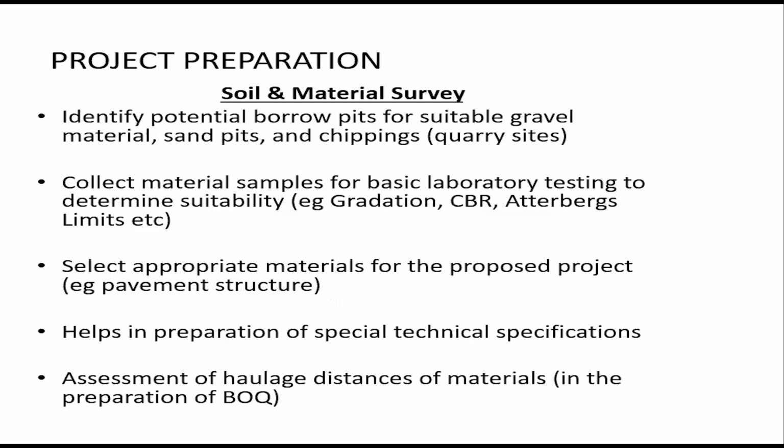Now, for the soil and material survey, you need to identify potential borrow pits for suitable gravel materials, sand pits, and chippings, that's quarries, for the project. You also need to collect material samples for basic laboratory testing to determine their suitability. That's gradation, CBR, Atterberg limits, among so many others, for one to be able to get the right materials for the project. Then you select appropriate materials for the proposed project.